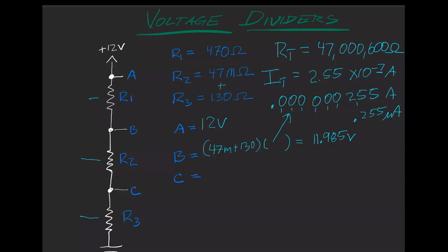And C is kind of unimportant. B here, with this high resistance, and just keep this in the back of your mind, we'll talk about this more in another video, is the same as a transistor turned off. So you'll notice that here's 12 volts, there's 11.985, and a very slight amount of current still does flow through this circuit. But nearly line voltage is felt at B with this high resistance.